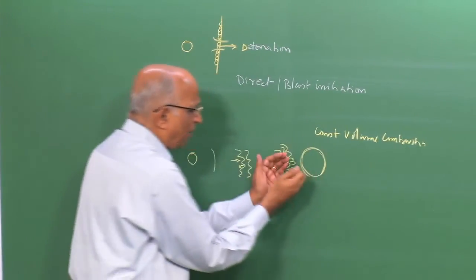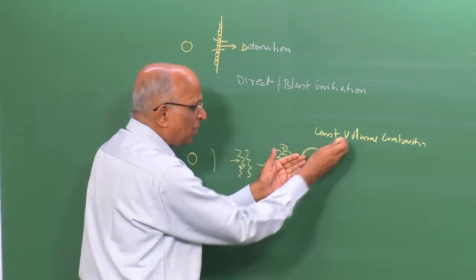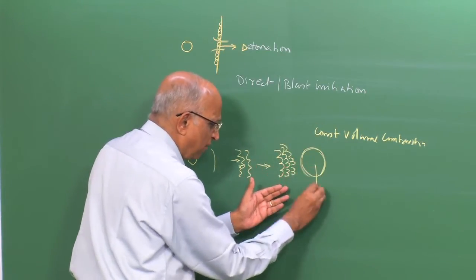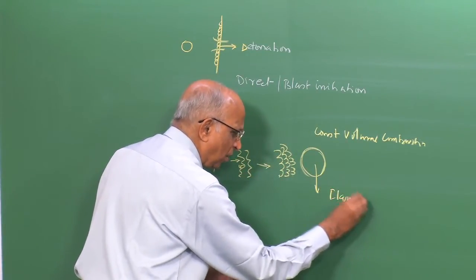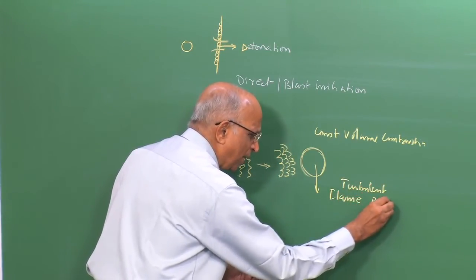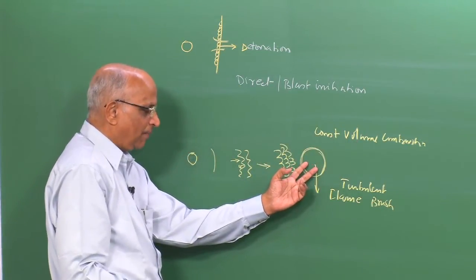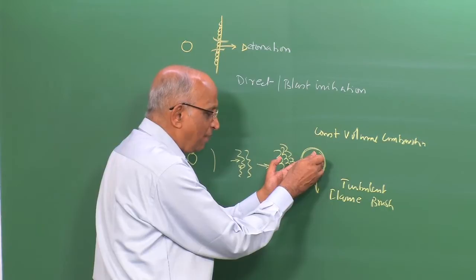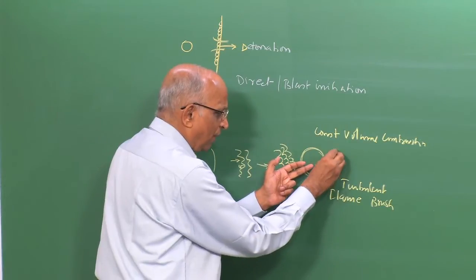When you say constant volume combustion, it is as if the whole thing is just burning, as it were, and therefore at constant volume I can say it is something like a sonic combustion which is taking place. This type of flame brush, in which you have intense turbulence, is moving at extremely high velocities, of the order of the sonic speed itself, but still it is not a detonation. When the chemical reaction times are such that it is able to form a shock wave,